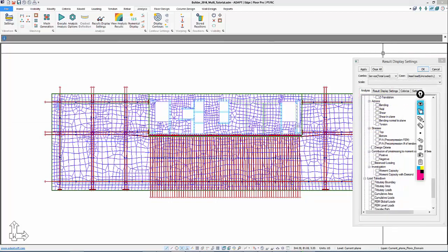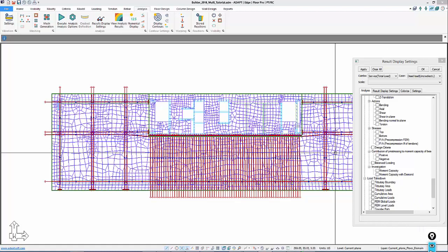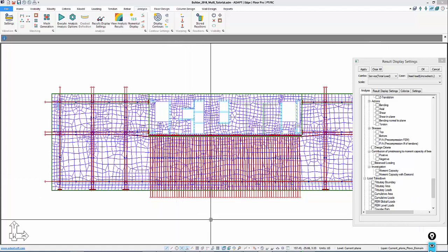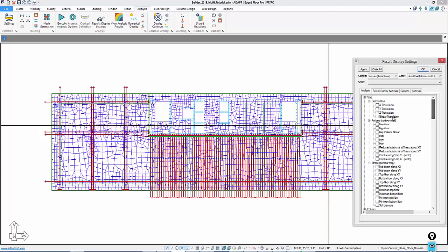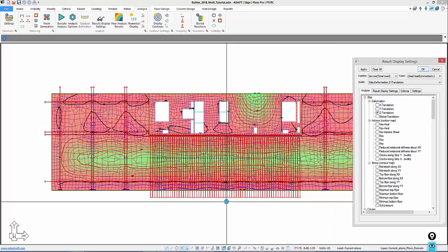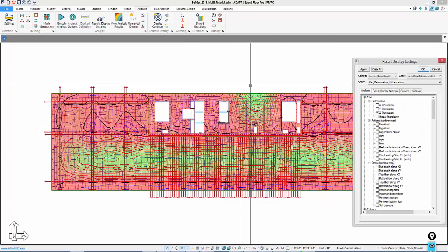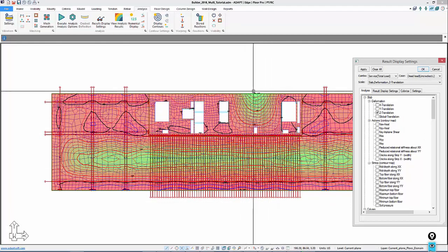So initially we looked at the deflection under self-weight only, and it was roughly 3/4 of an inch. That was without any post-tensioning. If we just take a quick look at the deflection under service total load with PT and with loading, we might be able to estimate where we end up in terms of long-term deflection just by using a kind of a gross multiplier. And you can see that the max deflection is still out in this region. We're going to ignore that region.